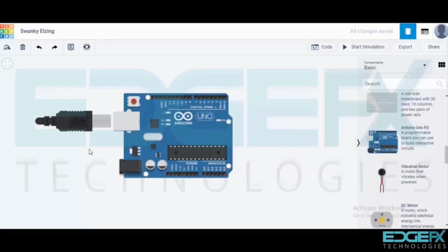For the power supply, we can use USB power supply 5 volts or 9 volts. This 9 volt is again converted using a 7805 voltage regulator to 5 volts. The Arduino works on a 5 volt DC and it's got an Atmega 328 microcontroller and a 32 KB flash memory. Now, let's see a few examples of code.